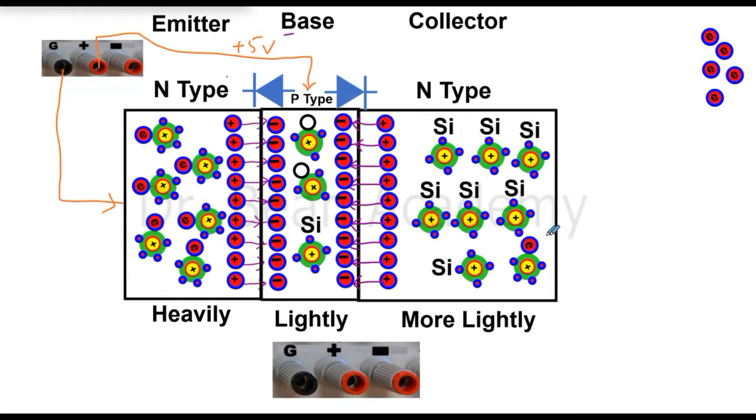For the collector, I connect it with the positive terminal here of the power supply, and I set this voltage at +2. And of course, the emitter is common because this is common emitter mode. So the emitter is common.